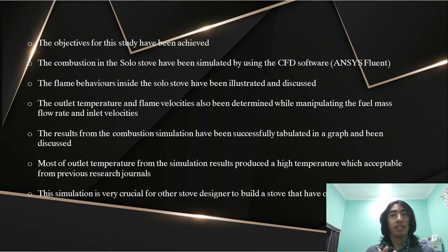As I mentioned, I cut some critical regions and a plane, and also plotted the temperature against height of the stove. The outlet temperature and flame velocity were also determined by manipulating the flame mass flow rate and inlet velocity. The results from the combustion simulations have been successfully tabulated in a graph and discussed.